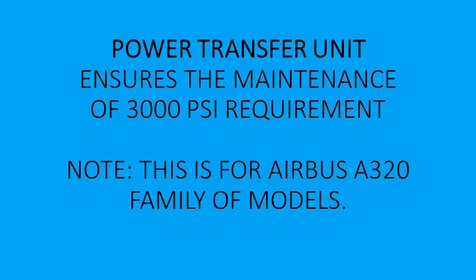The HP manifold, remember to mention, but you get high pressure. And I'm going to talk more about the high pressure manifold and low pressure manifolds. But here, the high pressure manifold has ports, which connect it to the other parts of the system. The system pressure inlet has a filter with a filtration rating of 15 microns. There's also a check valve to stop the flow of fluid in the reverse direction.